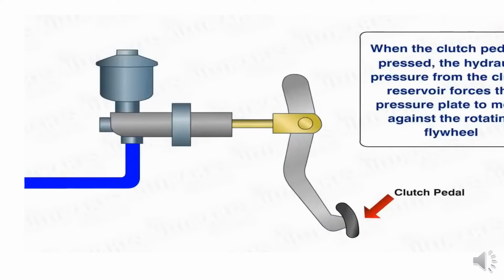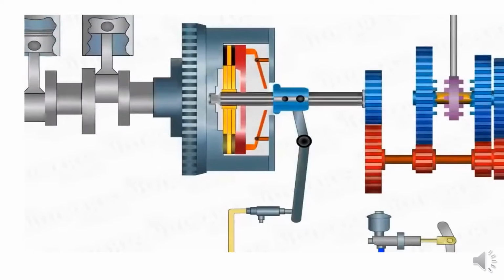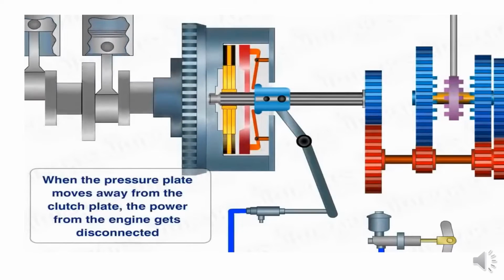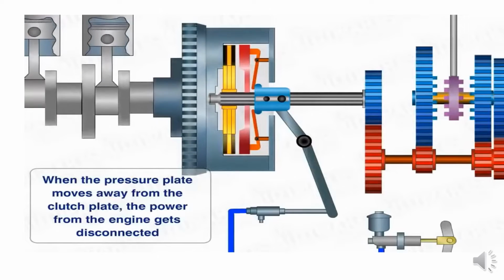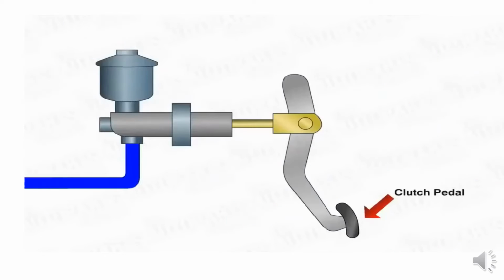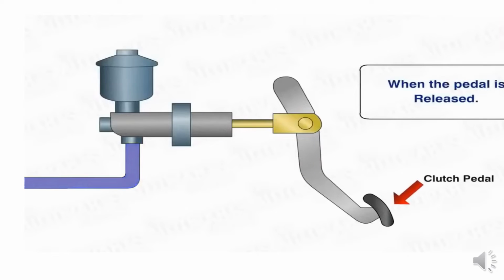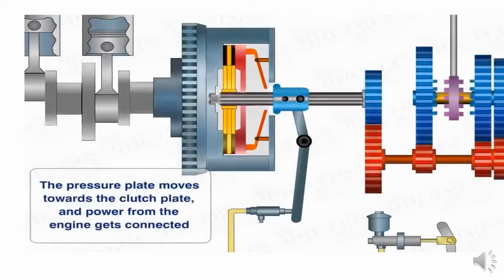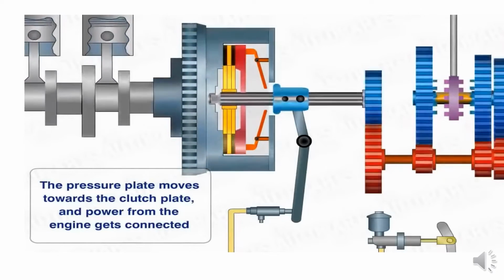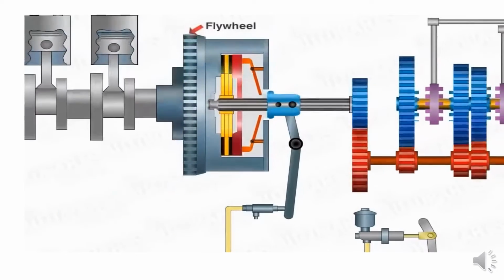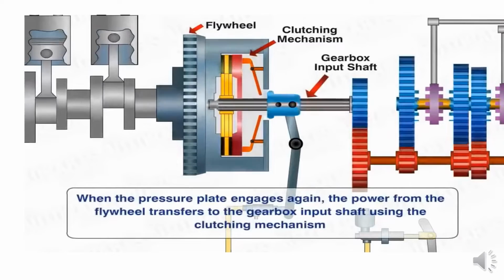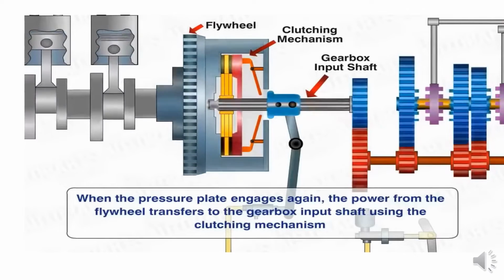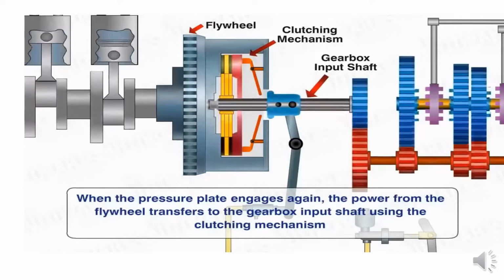It's an engine running. Power is produced from the engine, right? So the piston is moving up and down. The connecting rod oscillates and the crank is rotated. The piston's reciprocating motion is converted to oscillating motion by the connecting rod, and the connecting rod's oscillating motion is converted to rotating motion by the crankshaft.